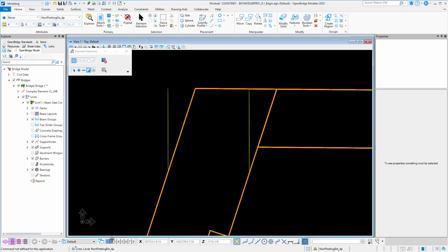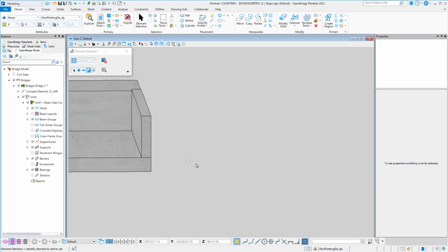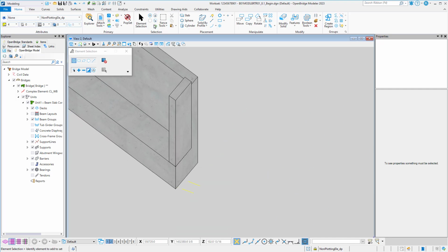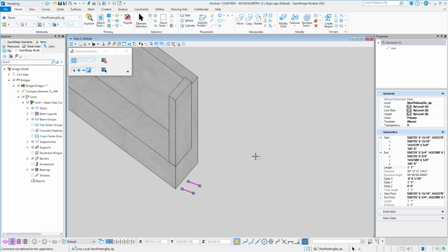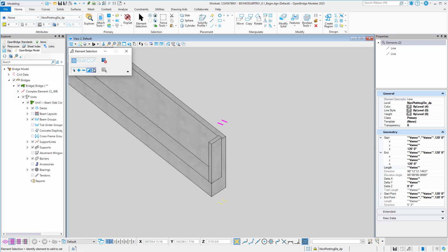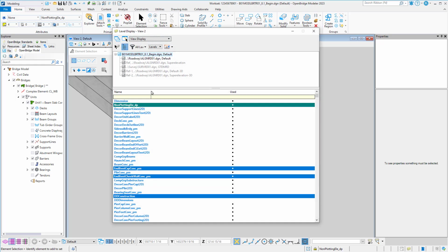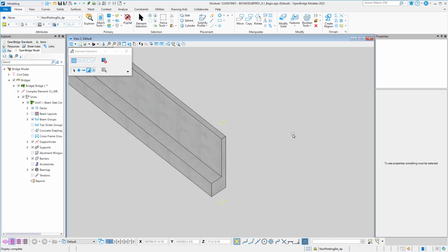With that now done, I'll go back to view 2 and copy these lines 15 feet up as before. Of the 3 mentioned modifications needed for the left side of the end vent before, we will start by trimming the back wall. Let's turn off the end vent cheek wall concrete PM level to get a better view of just the end vent cap and back wall.